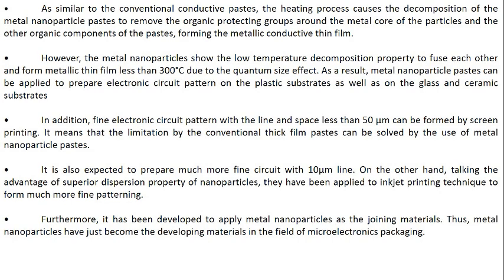They also allow fine patterns with lines under 50 micrometers via screen printing, overcoming limitations of conventional thick-film paste. Looking ahead, we are targeting 10 micrometer lines and leveraging nanoparticle dispersion for inkjet printing's ultra-fine patterns. Plus, nanoparticles are now used as joining materials, making them a rising star in microelectronics packaging. Let's explore their potential.